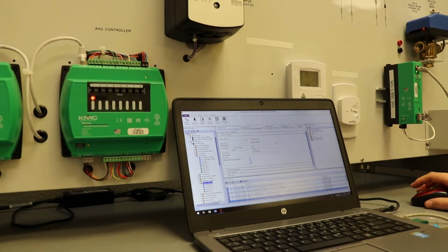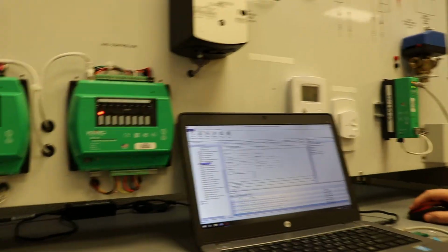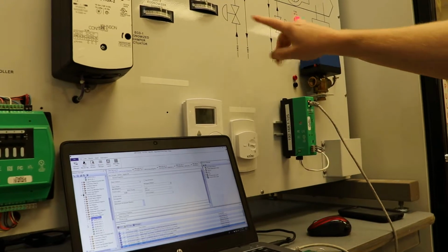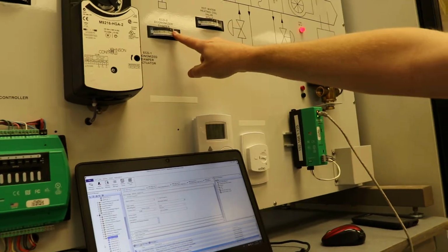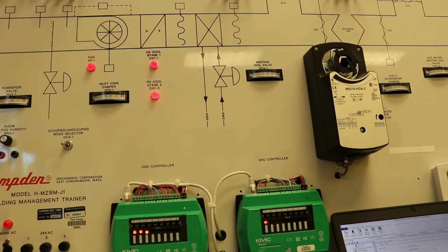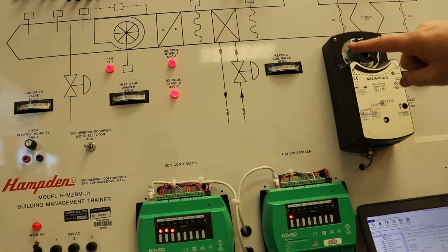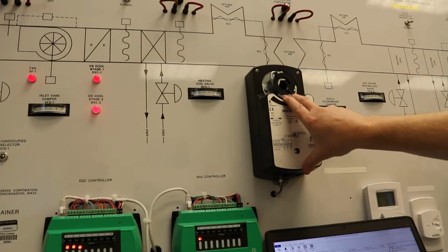Again, let's go to air handler 1. I thought you had only set up this side, but you have both of them. Yes, both sides are operational. So this here would be an air handler with both a heating and cooling coil on it, and with an economizer damper. Now this side, however, is an air handler that has hot water heating, but it has 2 stages of DX cooling on it. So this one actually works a little bit differently than this one would. Also, this one's got a physical valve on it, and this one has a physical damper actuator on it.